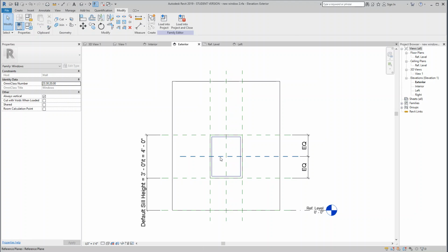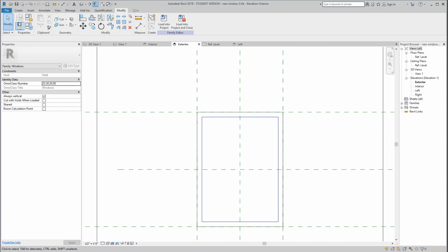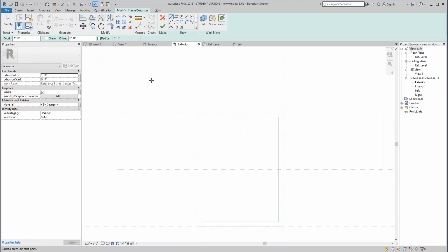We're going to build a little error in here. Our windows are going to be exactly the same size, so I can make a quick construction, but they really should overlap the sill width. So let's go ahead and make our top window component here now. So I'm going to create once again an extrusion. I'm going to use our rectangle tool, go up into the top corner, come down to the bottom corner, and before I click off anything, I'm going to attach the lock boxes to it. And then we'll do that same technique of creating an offset. So I'm going to use the offset tool and then join those.